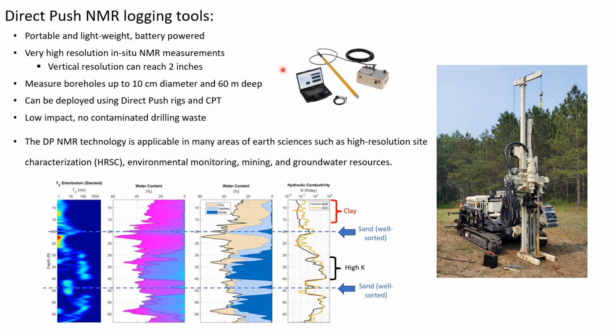So these tools can be used in boreholes up to 10 centimeters in diameter and 60 meters deep, and they also can be used in combination with the direct push and CPT instrumentation, and provide very low impact and non-contaminated drilling waste.